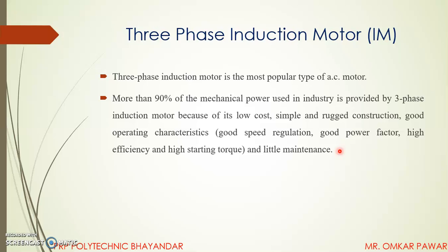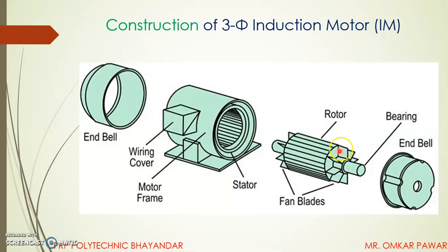So this is basically the workhorse of industry. Now, the construction of the three-phase induction motor. In construction there is a motor frame, the outer motor frame. Next is the stator, which is attached to this motor frame and is a stationary part.